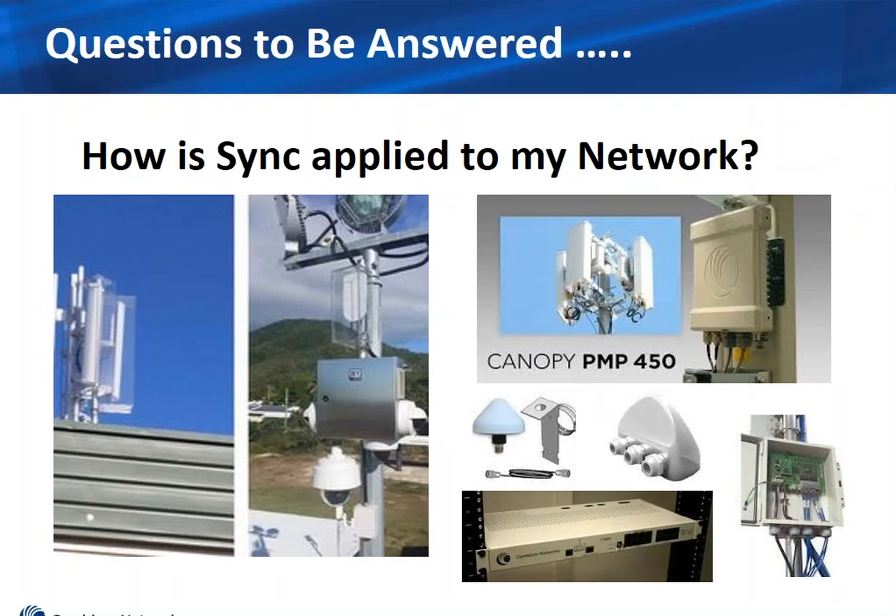So how is sync applied to my networks? Very simple, very quick slide, but basically we talked about GPS. So a number of these radios that you see here, let's take the Canopy 450 picture in the top right-hand corner. You see multiple access points deployed on a structure there, and they're all being timed by a GPS that you see directly below it, or a device similar to that, as well as the access point, which is the radio piggybacked on the back of the antenna in that upper picture. It also has an onboard GPS built within the radio that can be utilized if needed.